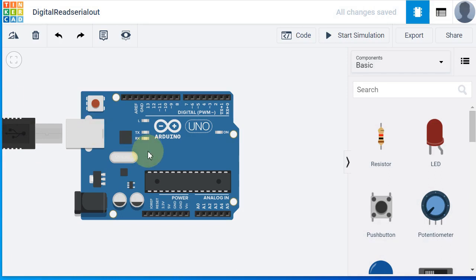Now let me see the different forms of digital inputs we can give to the Arduino. One is using a push button. We can give digital input using a push button, selector switch, relay contact, or anything else like that. The main point is that a digital input should have only two types of voltage status: either 0, or 3.3 volts or even 5 volts.